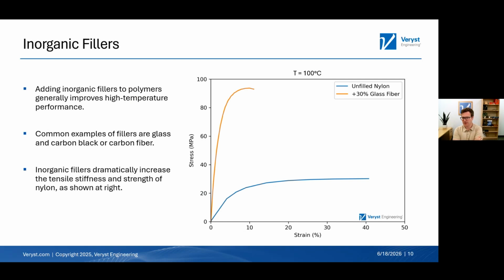And so, a question you might ask is, if I have a material, what are ways that I can change its mechanical response at different temperatures? And I like to highlight the presence of inorganic fillers. This is an extremely common strategy for trying to create polymer materials that have better mechanical properties at elevated temperatures.